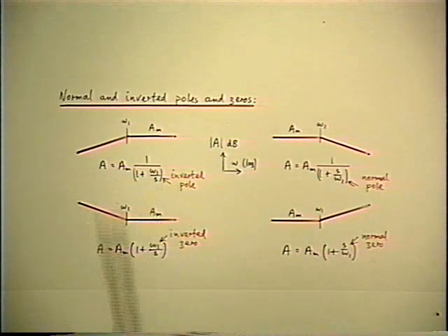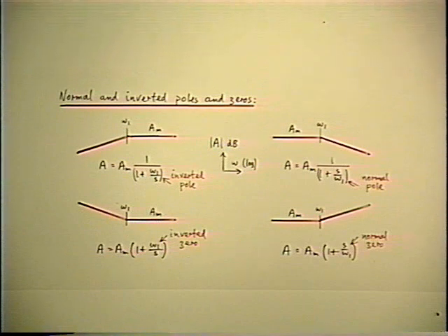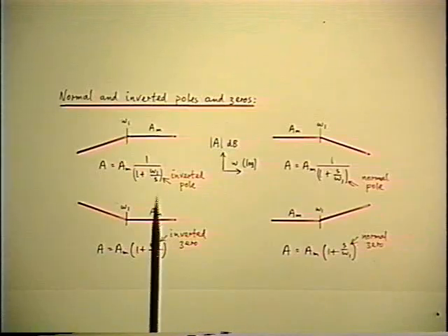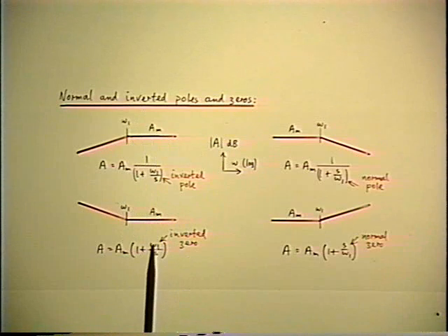And most people don't use this notation, which is okay. You can get by perfectly well without it. The point about inverted pole and zero representation is that why not take the advantage of the symmetry of the picture? Because very often what's important about frequency response is the flat part, which is the mid-band gain, for example.